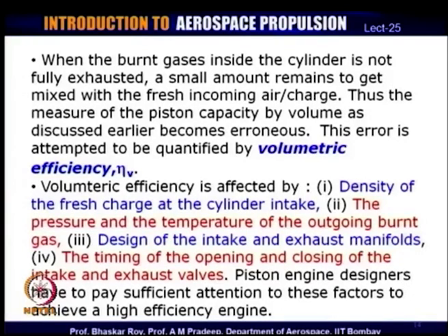So, the engine needs to be designed to create very efficient intake and exhaust manifolds, otherwise it will affect the volumetric efficiency and the timing of the opening and closing of these valves. This is the engineering that needs to be built into this particular piston cylinder arrangement, otherwise it will affect the volumetric efficiency, and sufficient attention needs to be paid to this by the piston designers.